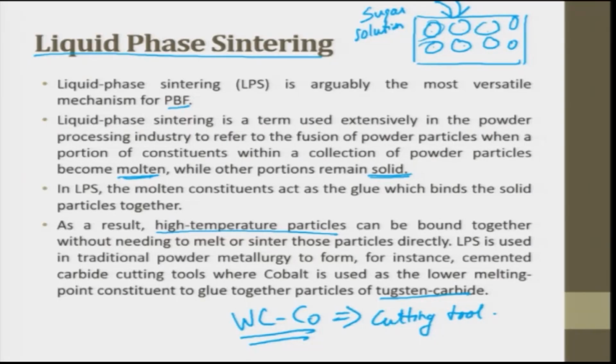It is rapid manufacturing. You just mix whatever you want, tungsten carbide plus cobalt. The cobalt content is varied depending upon your requirements. With more and more cobalt, the product you make can take tougher and tougher loads.